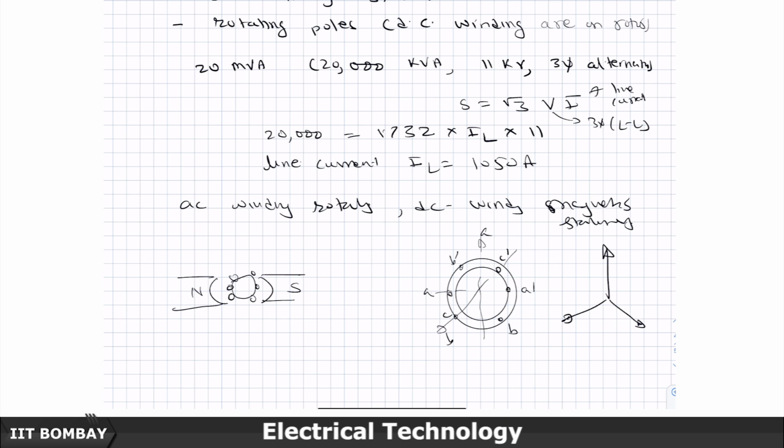So I get 90 degrees here, another 30 degrees here, then the corresponding B phase conductor came here, and I have to go another 120 degrees here. So 60 degrees here and then 60 degrees here. So what I marked as C dash is incorrect, this will be C. So the C conductor will come here and the corresponding C dash conductor, the opposite conductor, will come here.